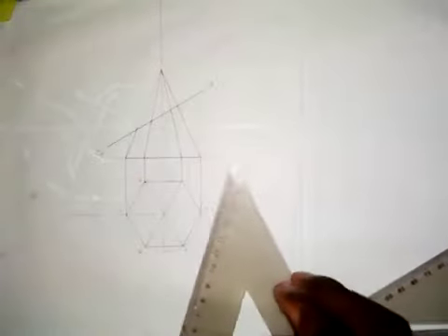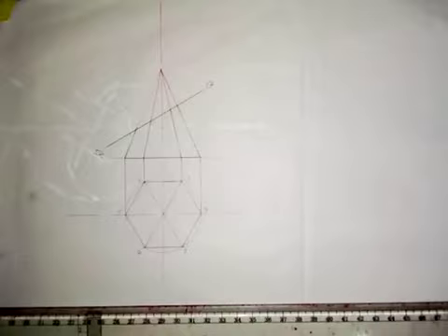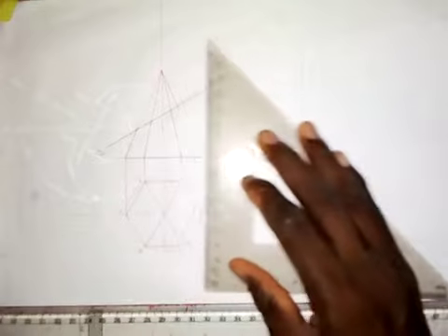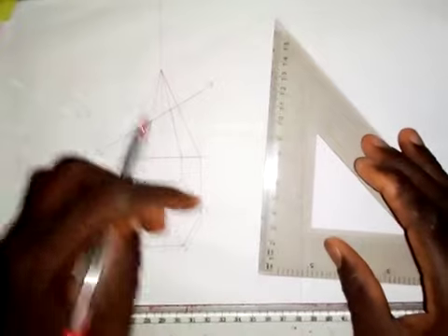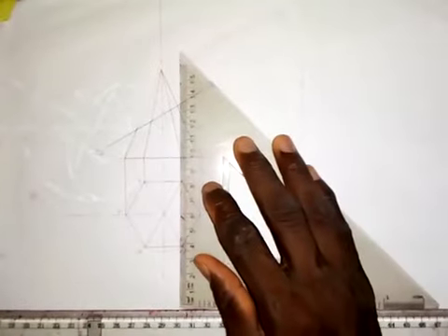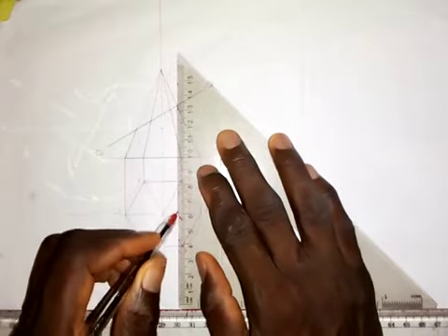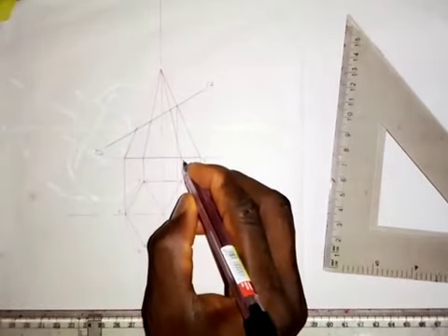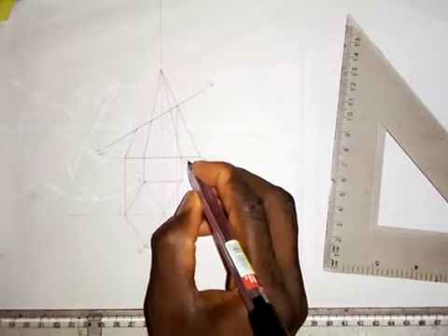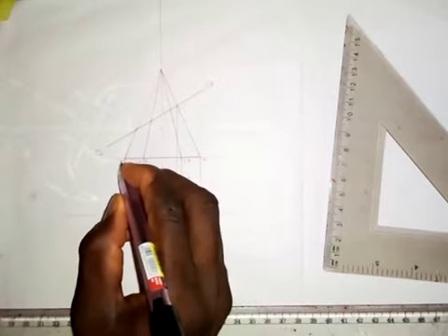Alright, so having done this, the next thing that we are going to do is to draw the complete plan. So this is the elevation now. As we are instructed, we have drawn the elevation. So the next thing to do is to draw the plan, because by the time we remove this part that is cut off, we are going to have a rough surface. That roughness has to be shown in the plan, and that's what I'm going to do. So from this point here, draw a vertical line. If you look at this vertical line, this is 2 and this is 1, 3. So this is 4, 6 and this is point 5 on the pyramid.